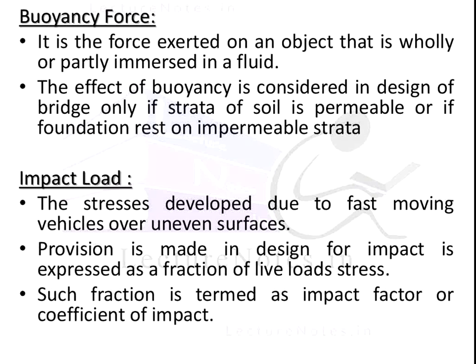Second load, impact load. These are the stresses developed due to fast moving vehicles over uneven surfaces. Impact load means the load is suddenly applied on the surface of the object. Provision made in the design for impact is expressed as a fraction of the live load stresses. Such a fraction is termed the impact factor or coefficient of impact.